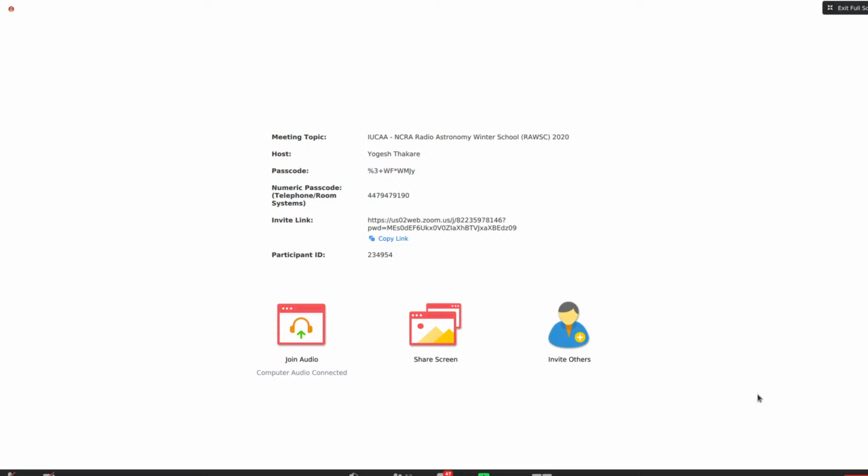reflections. And so to keep the system simple, it's always advisable to go to an open area if you can find one. If you cannot, of course, be mindful of the possibility that other reflections might contaminate your measurements. In that case, you're absolutely right. Can we use theoretical equations related to a ten-ray model or something similar? Yeah, you can, but there is no limit to it. It's not exactly a one-ray or two-ray or n-ray model. It's the entire Fourier optics. It's not ray optics anymore.